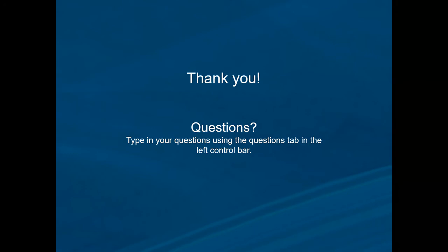A question about how reliable are humidity sensors over time? Yeah, I think you want to make sure that you are at least annually calibrating those. Obviously, the quality of the sensor may have more to do with it. They probably have recommended numbers. Typically, your more typical systems are plus or minus 2%.